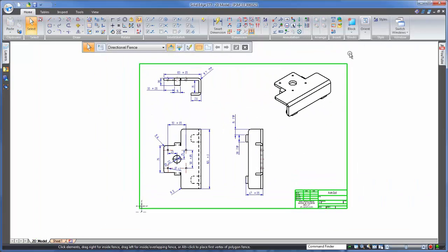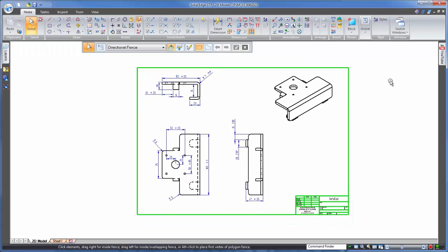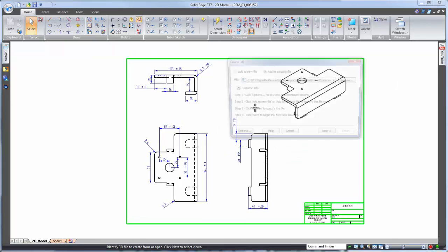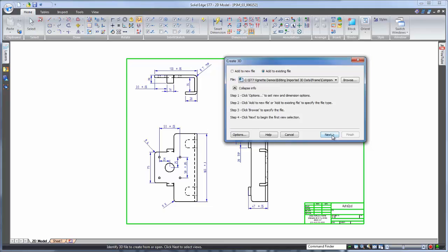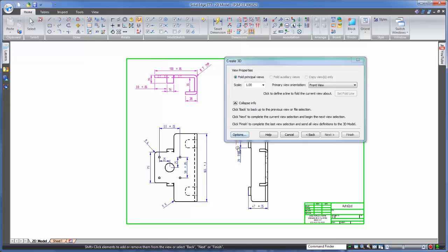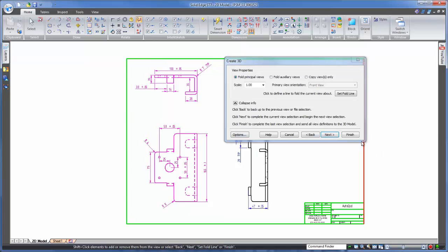Well, check this out. Once we open the DWG file inside Solid Edge Draft, we can then use a tool to help us get this done. In this case, we're going to grab the information we need by fence selection and then apply that information to our 3D model.